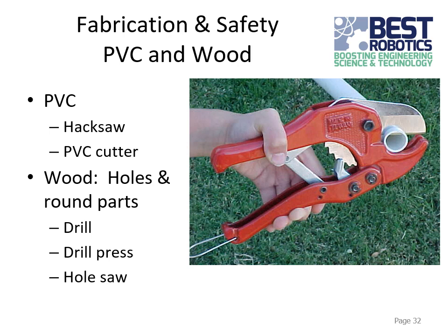So once you cut PVC, if it's an edge that's going to be exposed, then it's a good idea to clean it up with a piece of sandpaper or something to smooth it off. But if it's going to go into a PVC connector, then it doesn't matter. Nobody's going to see it. Nobody's going to care. So you don't need to in that case.